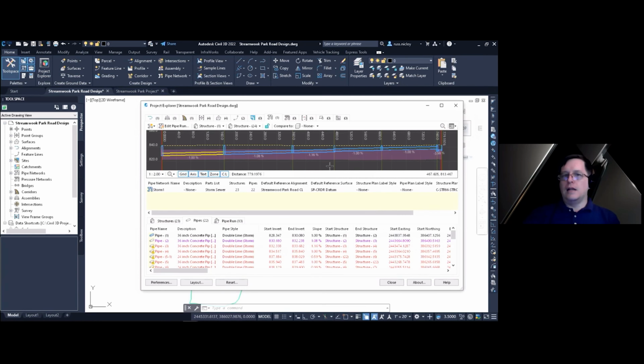Now, that being said, there are plenty of spots in Civil 3D directly. You can go into the data grid view and see that there's an error saying that you're breaking a minimum rule. In fact, we saw these rules earlier. If you hover over it here, it's going to tell you that the minimum cover of 6 feet is broken, and by how much. However, I don't know what the context of that is.